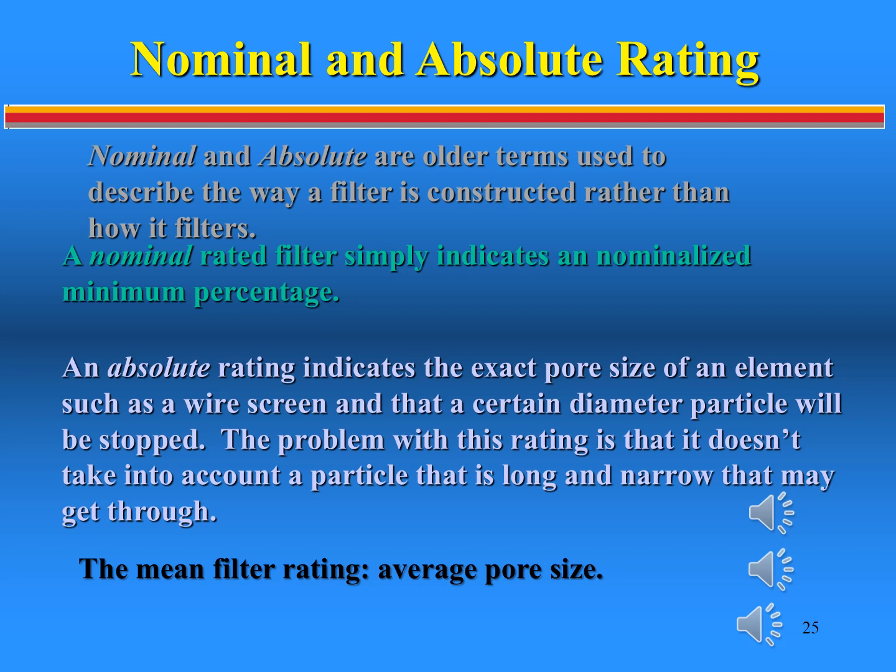The absolute rating shouldn't be confused with the largest particle passed by a filter under operating conditions. The absolute rating simply determines the size of the largest glass bead which will pass through the filter under very low pressure differentials and non-pulsating conditions. This does not usually apply in practice.